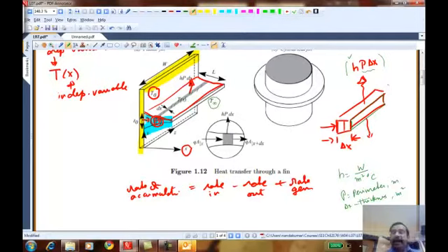Okay, and as we already talked about, on the left side I have heat coming in. I'm going to represent that as q, the heat flux. What is the heat flux that is coming through the left? And this is evaluated at x. So I'm going to put a subscript x to indicate that is the heat flux coming on the left side of my control volume. And on the right hand side, I have q at x plus delta x. That is the heat leaving the right hand side at x plus delta x, because that plane is at the position of x plus delta x.